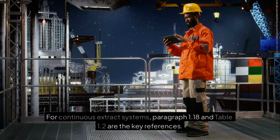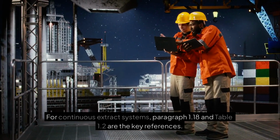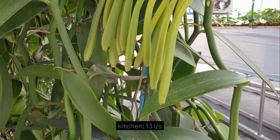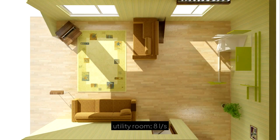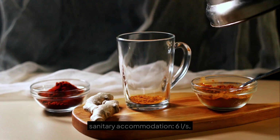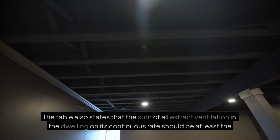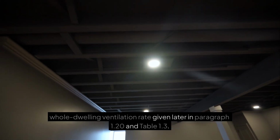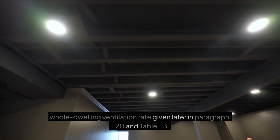For continuous extract systems, paragraph 1.18 and table 1.2 are the key references. The minimum high rates are kitchen 13 liters per second, utility room 8 liters per second, bathroom 8 liters per second, sanitary accommodation 6 liters per second. The table also states that the sum of all extract ventilation in the dwelling on its continuous rate should be at least the whole dwelling ventilation rate given later in paragraph 1.20 and table 1.3.